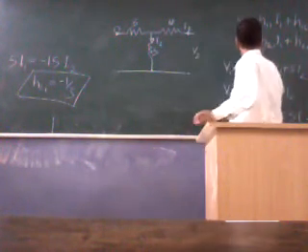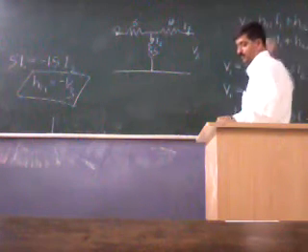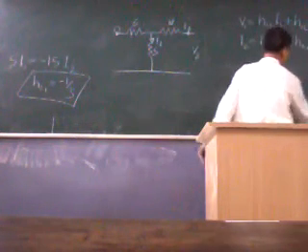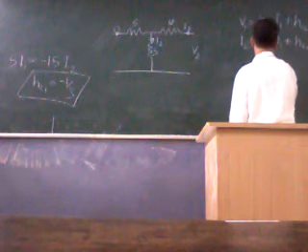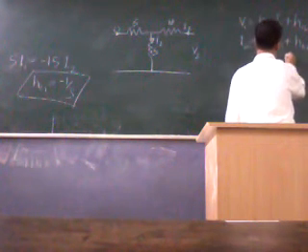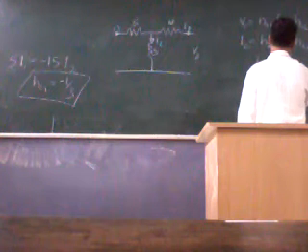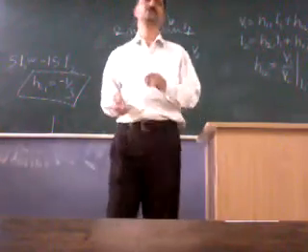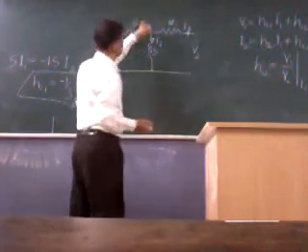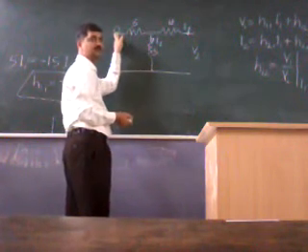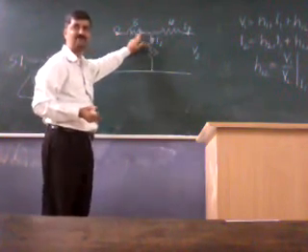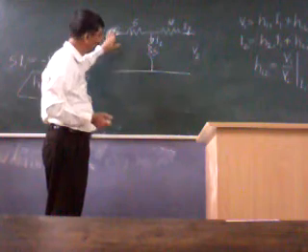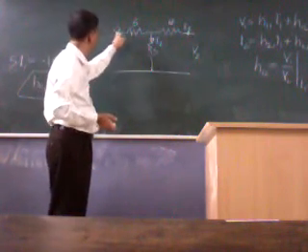V2 is here. Now what is H12? This gives me H12 equal to V1 upon V2 when I1 is 0. When I1 is 0, whatever is this voltage must be equal to this voltage. Why? What is the reason? Because this current is 0. So don't connect any source as such and don't include it in the loop.